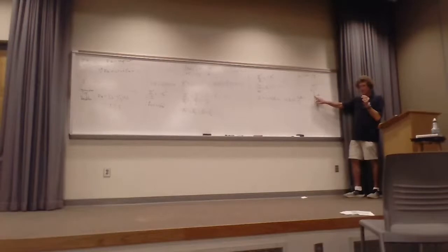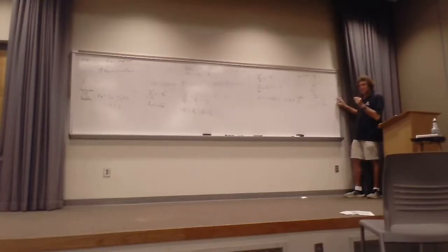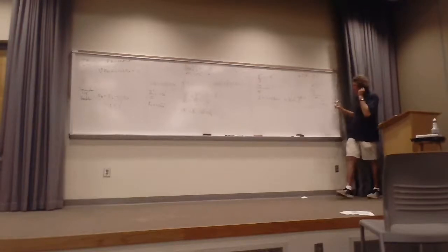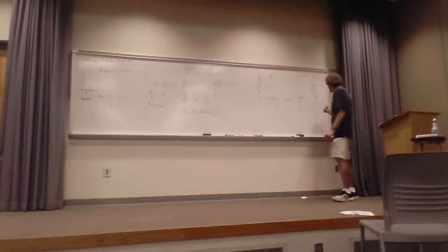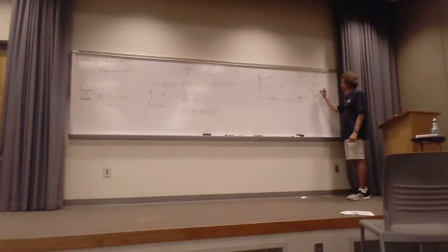It has to go to 0 there, right? And it has to go to 0 there, doesn't it, class? Mm-hmm. You might not be seeing this, but remember, this is a variation in x. So if you think right in the center of the guide, as you're moving this way, you can have E_z in this direction. But whenever you come to this edge, it's got to short out. Do y'all follow me on that?